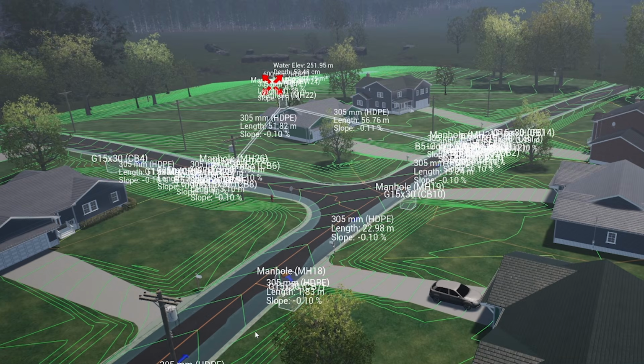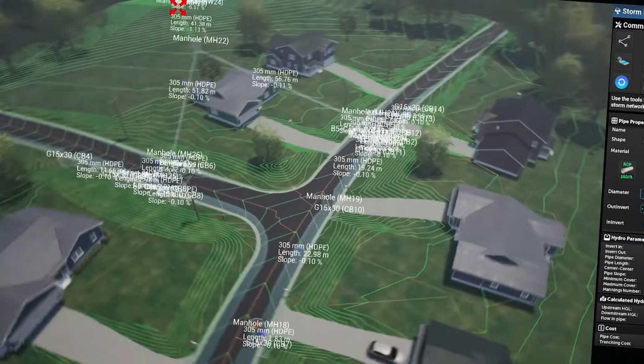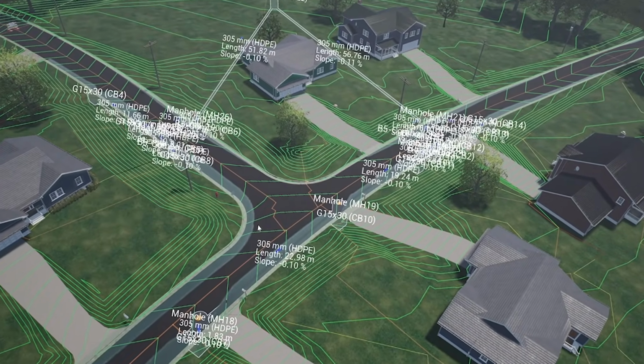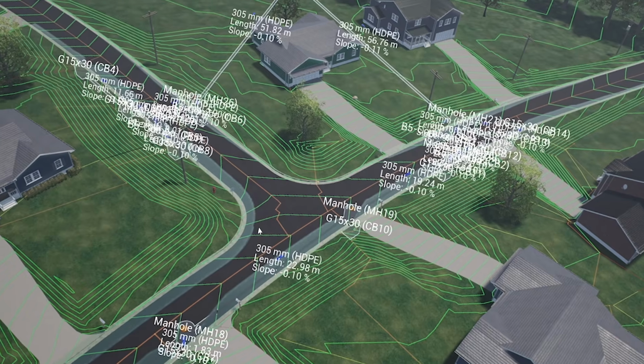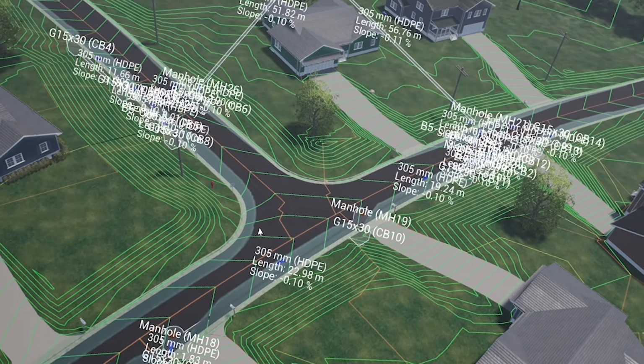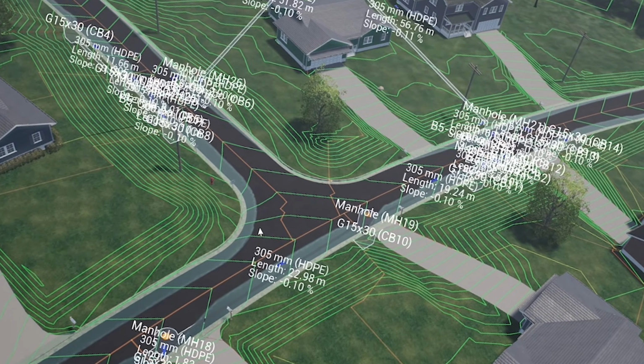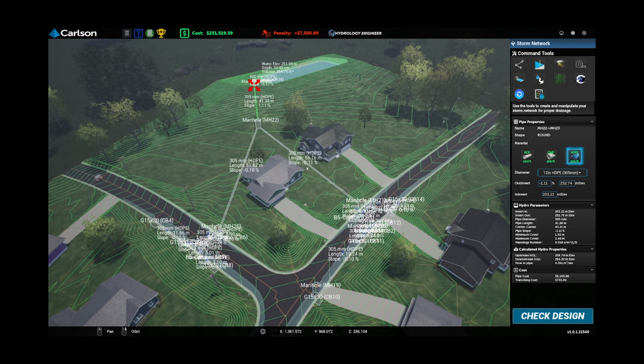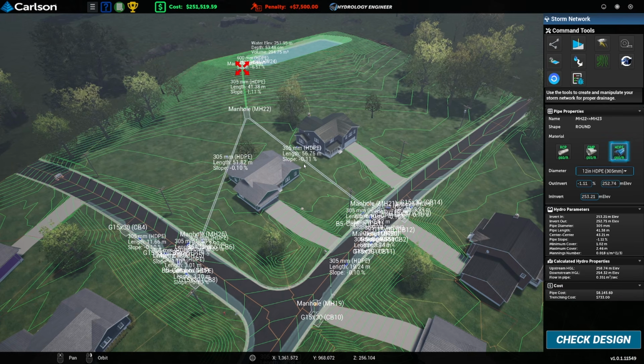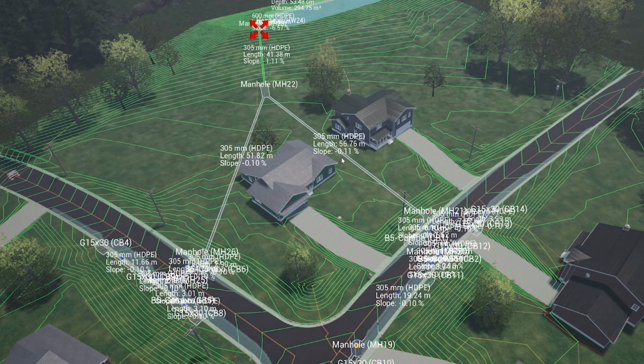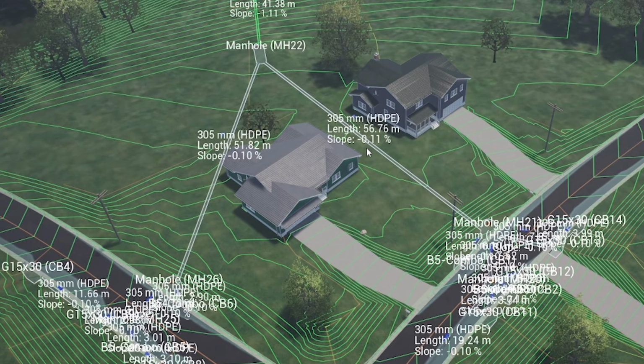So from the 1970s to nowish, we have rainfall data. People have actually been measuring it. But we're slowly finding out that during that period, because it's only about 50 years, and we're looking at 1 in 100 year storms, we don't know what the actual data is. We don't know what the worst storm in 100 years is going to be. So generally we just take those graphs and extend them to think, okay, if that's the worst in 50 years, keep the graph going. That's how much it's going to rain in 100 years.